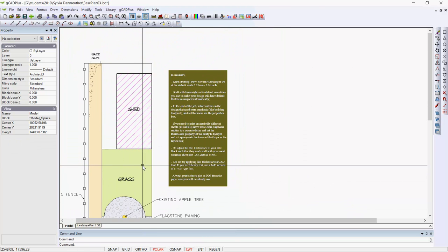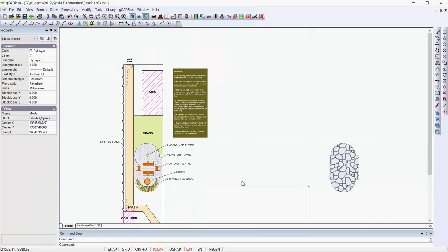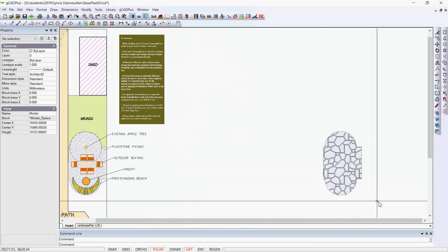I hope that helps just a little in understanding line weights. The simplest approach is just draw. Don't change anything, just draw, and then select those few entities that you want to give emphasis to and set their line weight without worrying about layers. But if you're going to use multiple drawing sheets of different sizes, then it's useful to put those same entities onto different layers.